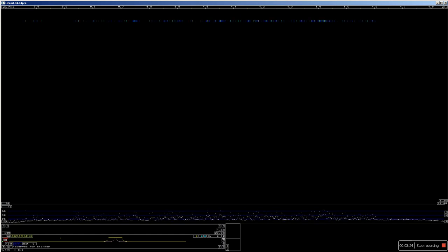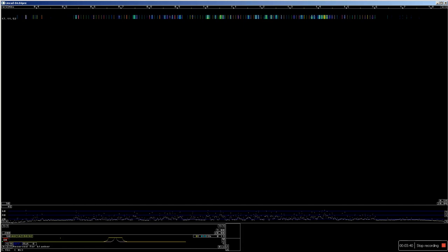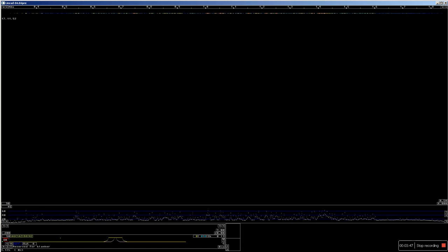And I want a different color scale, let's say 0.5 here, and allow Linrad to find the 0 point by right-clicking the box in the lower right corner of the waterfall, where it's now number 20, and right-click there, and Linrad decides 4 would be reasonable.